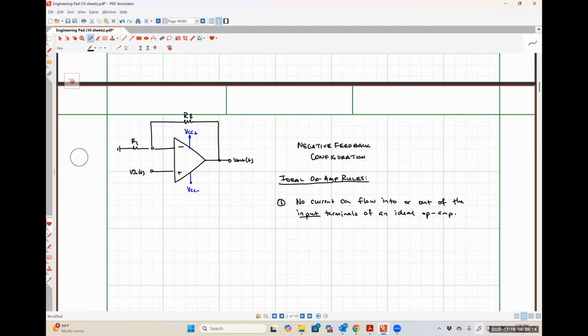So that's 10 to the 6 ohms for bipolar junction transistor technology, and 10 to the 12 ohms for metal oxide semiconductor technology. So if we use a kilo-ohm size resistor to bias this circuit and make our connections, it's roughly 1,000 to 1,000,000,000 times smaller than the internal resistance of the op-amp. So all of the current flows through the biasing resistor. Practically none of it flows into the op-amp itself, or at least the input terminals of the op-amp. So that's where that rule comes from.